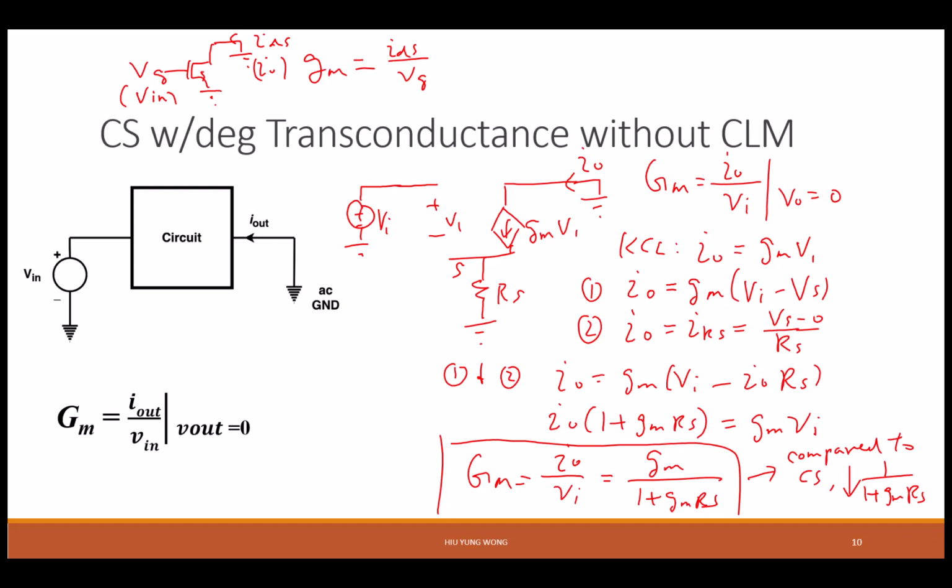It cannot be drain voltage. Otherwise, it won't be called transconductance. Right? Then you know it's drain current over gate voltage. If it's drain current over the drain voltage, we call it output conductance, or drain conductance, whatever. So transconductance for a transistor is the drain current divided by the gate voltage.